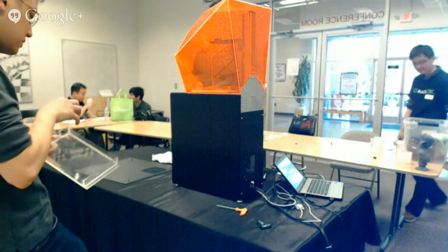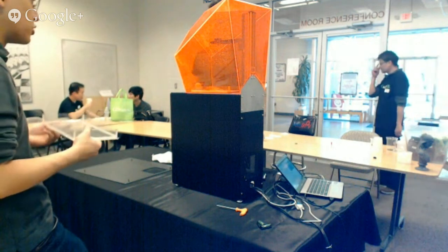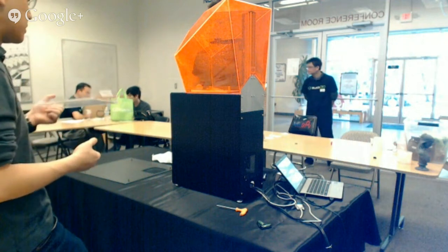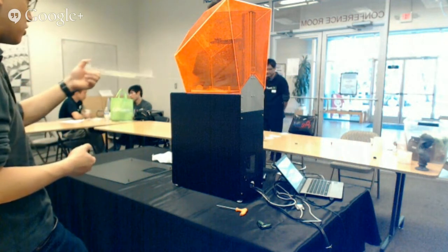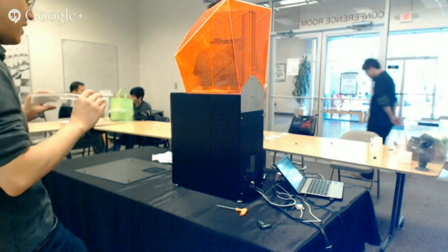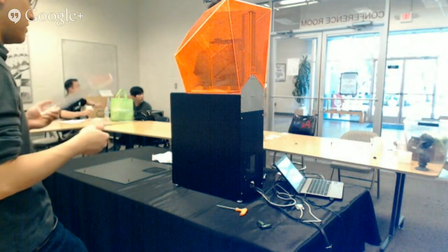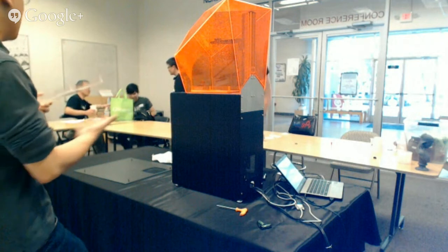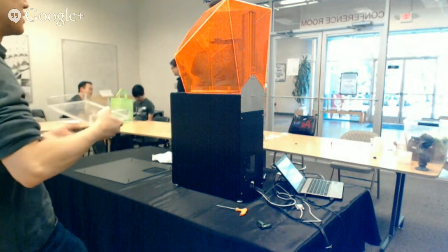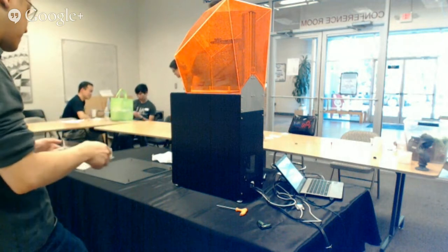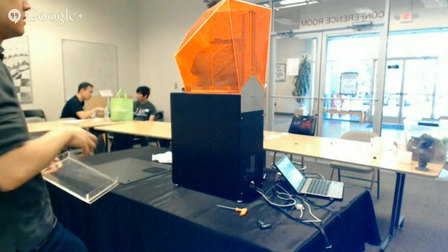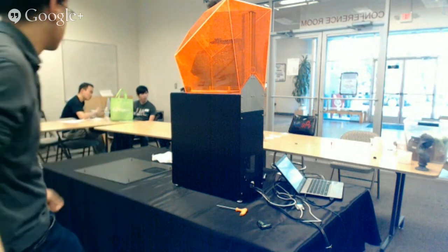And so if you want to print on Teflon, roughly speaking, there's only two ways to get that to work. You need a flex release system, and you either do it the way that Kudo3D did, which is their patented way of doing it, or you build a tension flex vat. There are lots of designs for these. You go to BuildyourownSLA.com. They're kind of complicated because it basically means you have just a film and you hold it in this brace that tensions it, so it's like a drum, right? And then you get less total flex, but flex in many dimensions as you pull off. And people say that works.